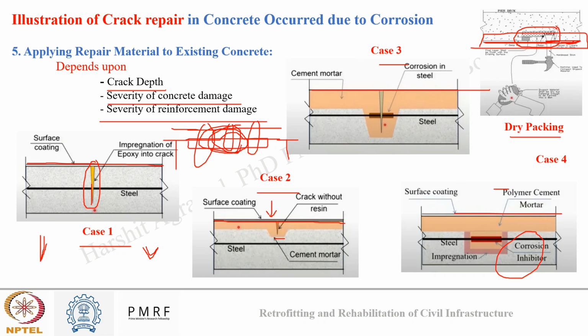Now once I have applied the additional reinforcement, I can coat this reinforcement again with a protective coating to make it more protective against external events. Once I have done this, I will apply my repair concrete and I will seal this.